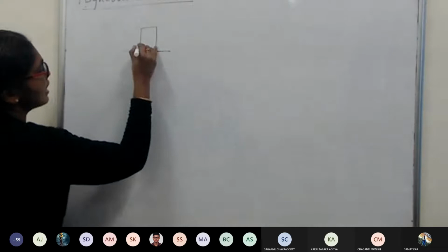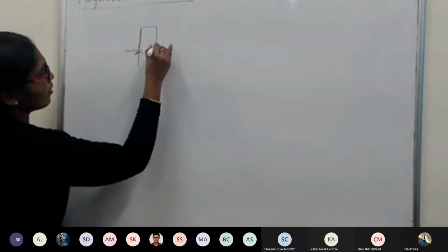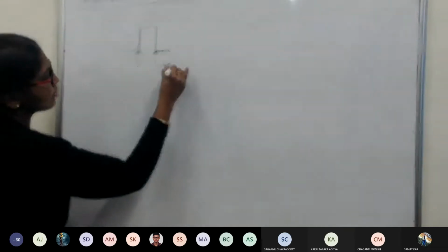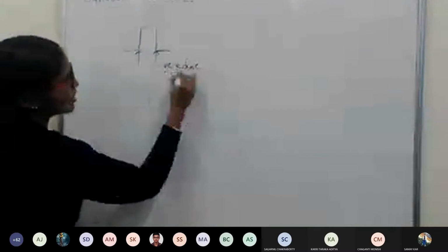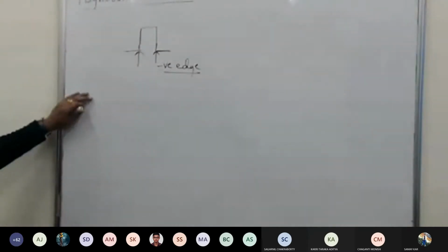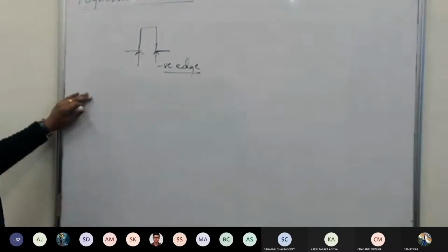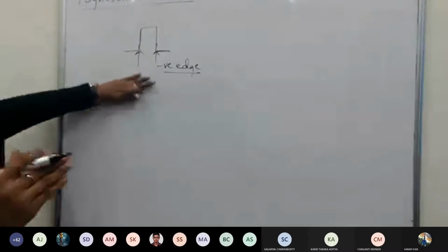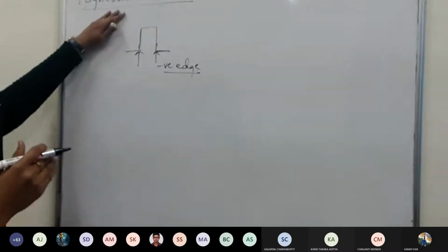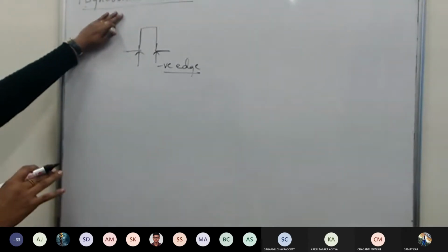And moreover, almost all asynchronous counters work with negative edge flip-flops. That means we have two edges, if you remember I was telling this. This negative edge will serve as the triggering edge. That means when the state goes from 1 to 0, it triggers the next flip-flop to do the action. Then like that it goes on. So we will try to analyze these asynchronous modes because there is no procedure involved in that.